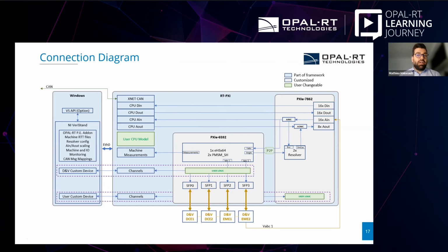From there, we have customers that actually build custom tables for the resolver pattern, to emulate faults. So it's a really flexible platform. If you want to have the resolver signals here and play with them, adding harmonics, behavior, unbalanced sequence, we have the capability in the system, especially with this FPGA, to generate all those signals as well.